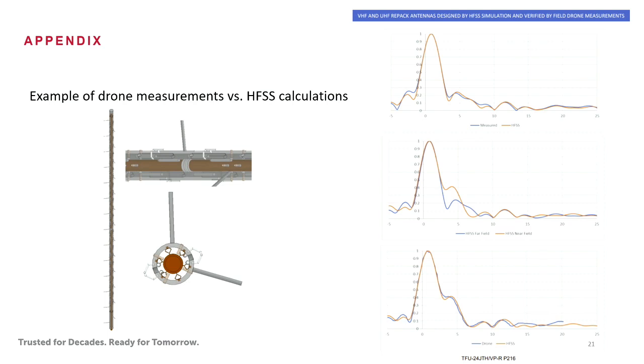So it would be really nice if you could take all the data within that 400 feet. Well, if you do that, you're going to get near field data for the elevation pattern. The good news is, because of the software, we have that in the software. So we can take your measured near field data and look at our software predicted near field data and see that they match, and then you can be confident that your far field data is going to be good.